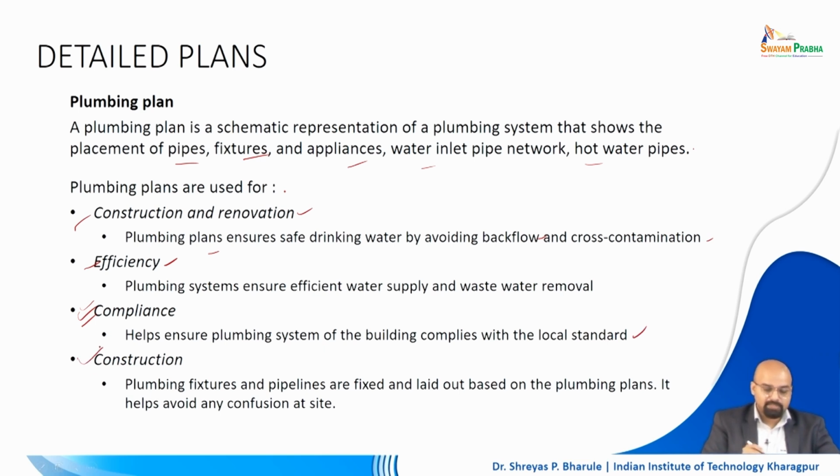Next is the construction guideline, right. So in case of your complete layout of a building, once you are done with the complete building, just before you plaster, you have to start with plumbing, particularly in case of creating concealed pipelines or concealed fixtures, say a concealed water cistern for flushing water for a WC.